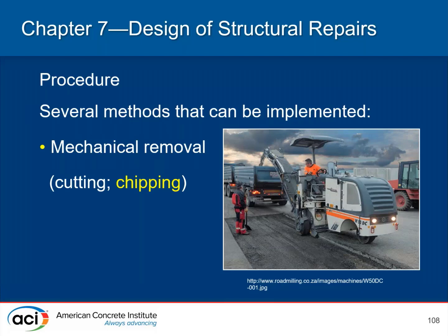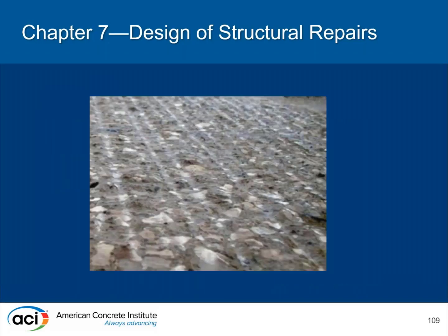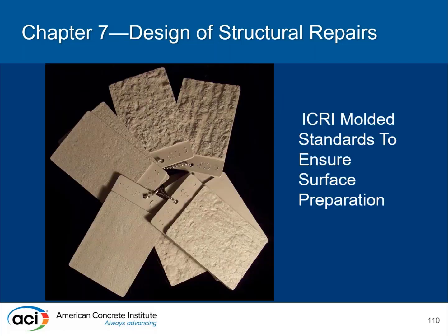Chipping is a mechanical removal approach that's often used to remove repair materials. And again, the idea is to remove deteriorated concrete. This is just a picture of the surface showing concrete that has been removed. The other critical aspect is when you use chipping hammers, etc., bruised or micro-cracked concrete occurs, which then has to be removed in order to create a good bond surface.